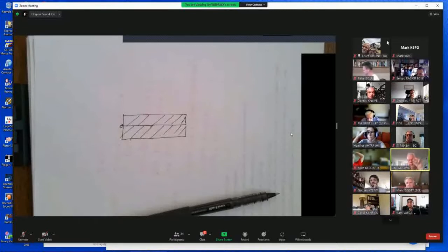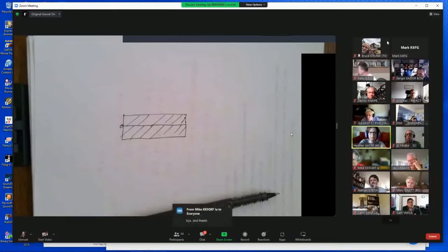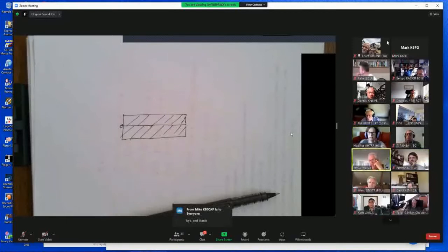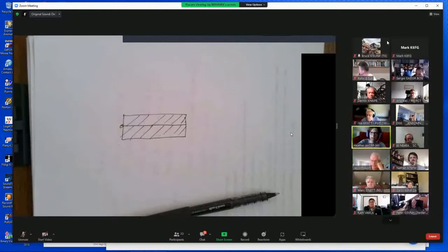I would suggest bandpass filters, as the gentleman suggested. Now, bandpass filters only operate on a particular band. Do you like 20 meters mostly, or do you operate on several bands? I've tried that one. I haven't really tried other bands yet. Okay, just what was convenient to try. The other thing is, and I've had it happen, how far away is the transmitter? Half a mile, probably about the same height as the transmitter at both of my locations.